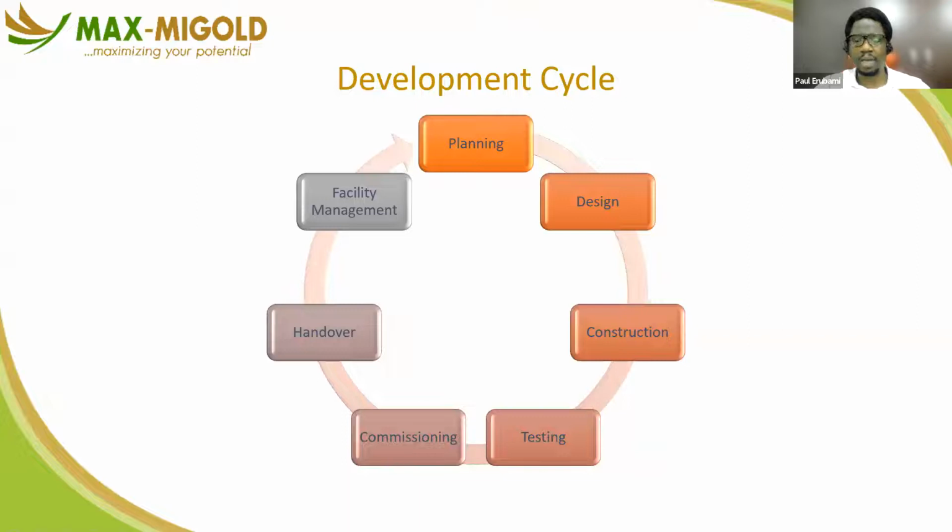In this design, you come out with certain outputs. Your input was the brief. What are your outputs? You have a set of design drawings as your outputs. The set of design drawings includes architectural, mechanical, structural, and so many other engineering drawings. So drawings are there, and then you have bills of quantities. The quantity surveyors will develop a bill of quantities for the project.